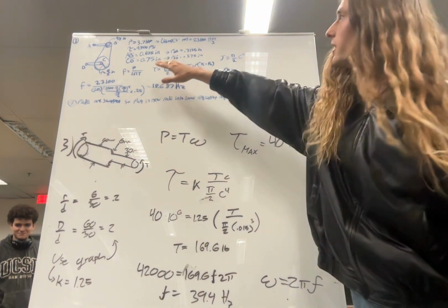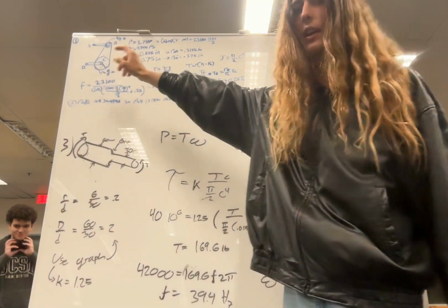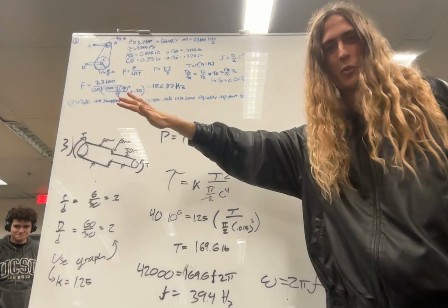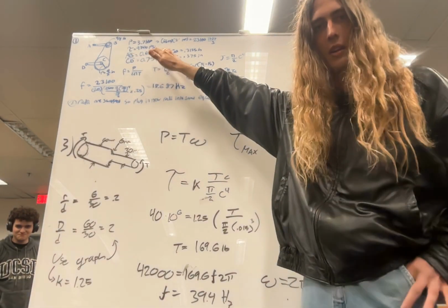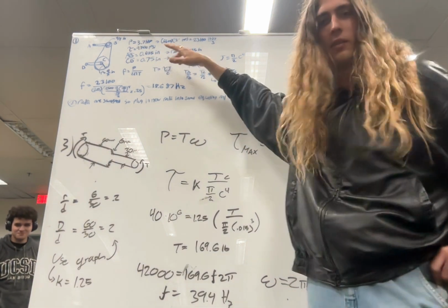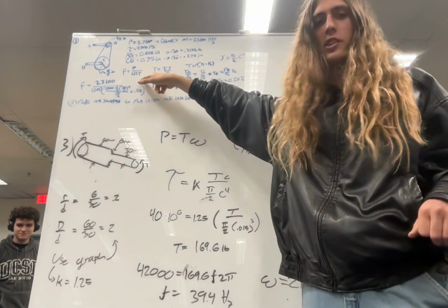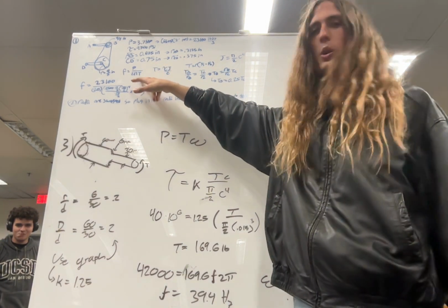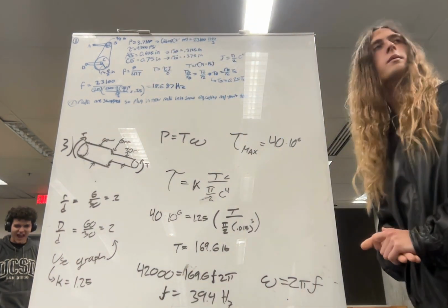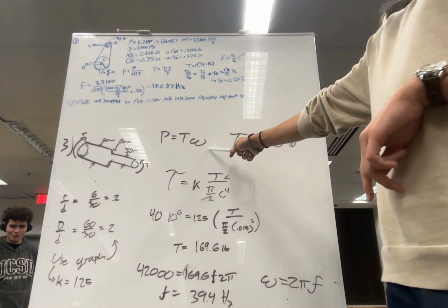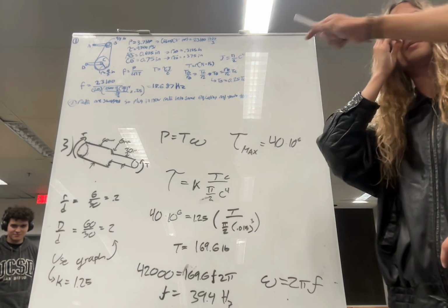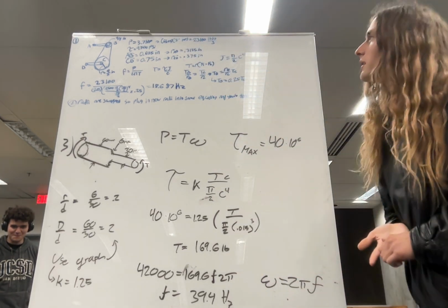And then we're also given these distances of the rods, the AB and DC. In our equations, we're going to have a C value, which is where we're going to use these, except you have to remember that these are diameter, not radius. C is for radius, so we're going to divide these by 2. And then this is the main equation you want to use. We use it in a couple of homework problems. Frequency is equal to power over 2 pi torque, or T. That's the same as power equals torque times frequency. Yeah, so we rearranged that.